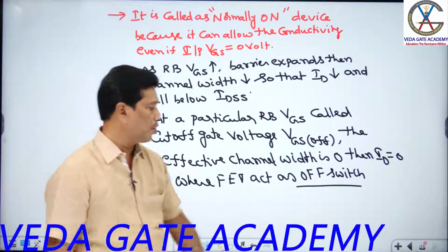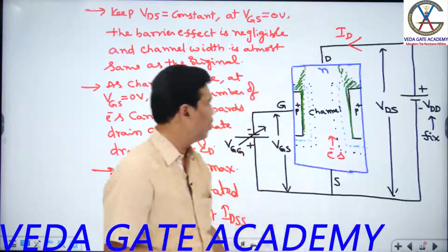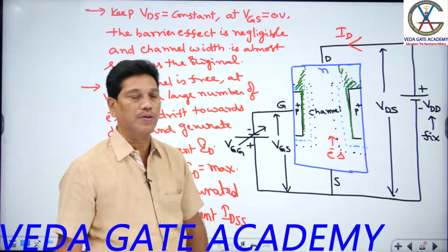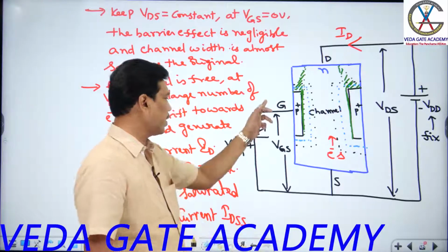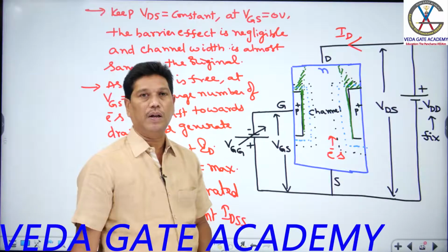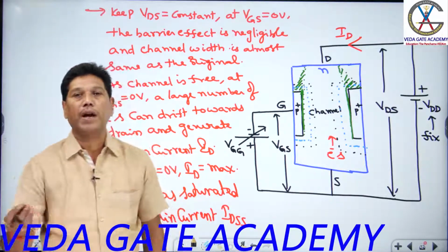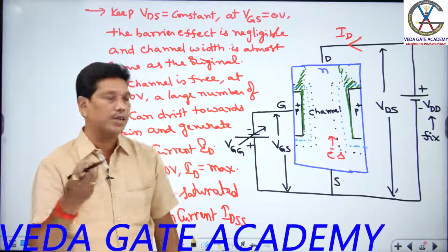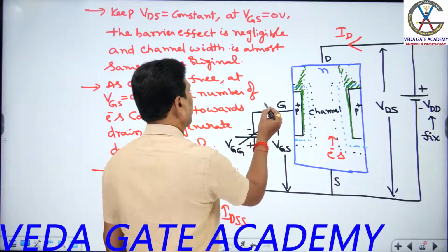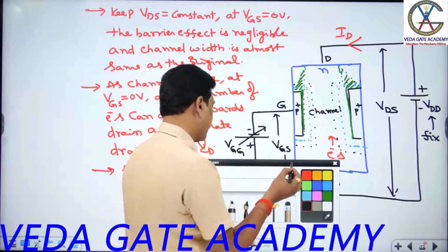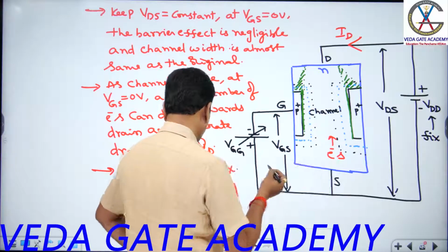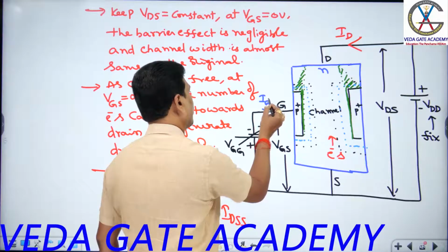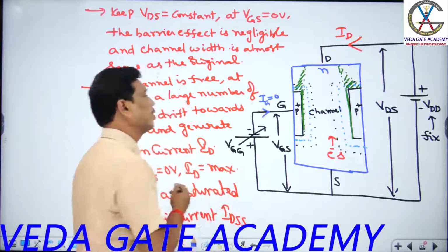Correct now? So now, this is the controlling of output current conductivity by the input gate voltage, students. Next, sir, the input gate junction is reverse biased. According to the PN junction in reverse bias, only minority current can flow. Ideally, the FET body does not allow any minority current, so for the ideal condition the gate current should be 0.